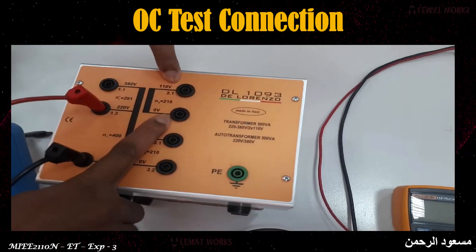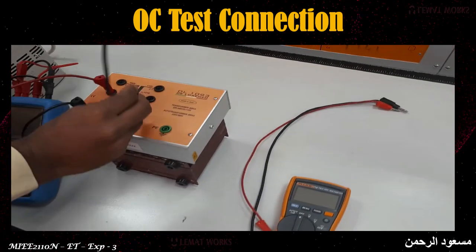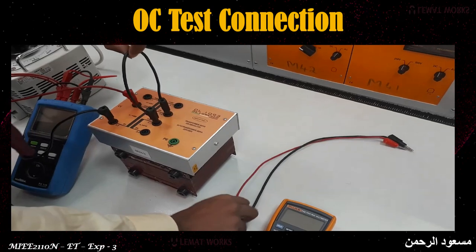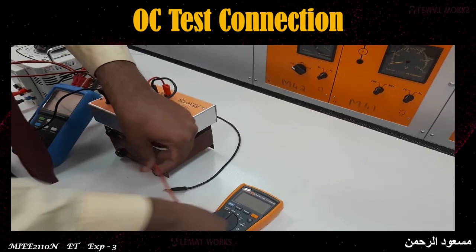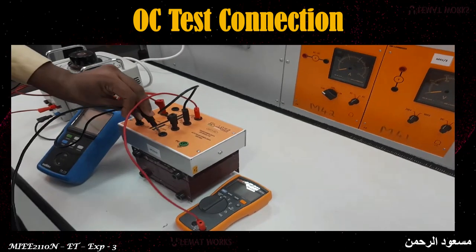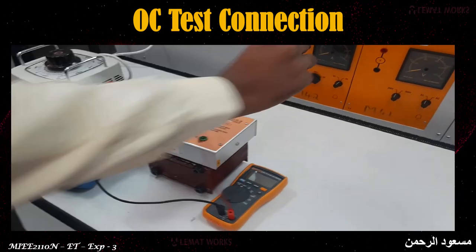Now coming into the secondary side, we have two coils, each rated for 110 volt. So to get the 220 volt coil, single coil, we are going to connect it in series like this. So now the coil is connected in series. This point is 220 volt point, it is connected to the voltmeter, and the voltmeter's neutral point is connected with zero potential point of the secondary winding. That's all about the connection of OC test, open circuit test.